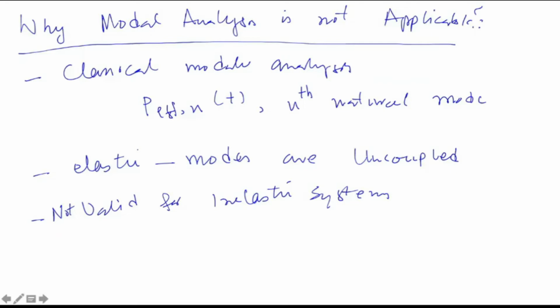So this weak coupling of modes permits the development of a procedure. As I mentioned, the modes are coupled for the inelastic system. They are not uncoupled anymore, but the point is that the coupling is weak. If the coupling is weak, the good news is that, just like the elastic case, we can treat each and every mode separately, and we can do the nonlinear analysis of the system.